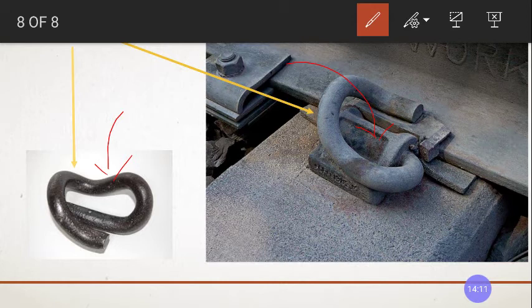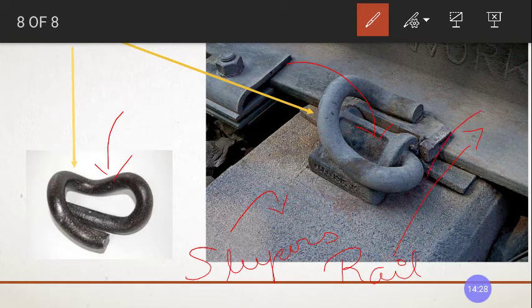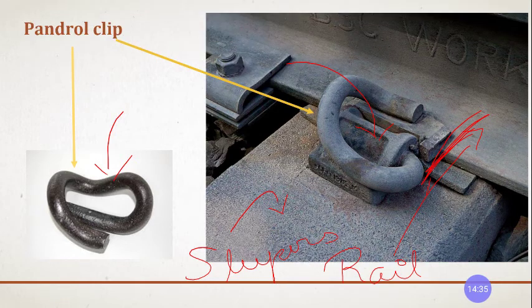Right? This is how it is. This is your rail. And this is your sleeper. It is connecting the sleepers as well as holding the rails and sleepers together, right? So that proper stability is provided. This is how the Pandrol clips look, and it is very easy to remove and place again. This is all about the sleepers, right?